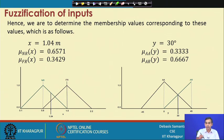So, here is an example of how the membership values for the two inputs, distance and angular orientation, can be calculated. The calculation shows that the membership value for the distance x equals 1.04, which belongs to the fuzzy state Nr, can be calculated as this. Similarly, the membership value for x belonging to the fuzzy state Fr can be calculated like this. Likewise, the membership values for the other input y equals 30 degree, which belongs to the fuzzy state AA, can be calculated like this, and AR can be calculated like this.